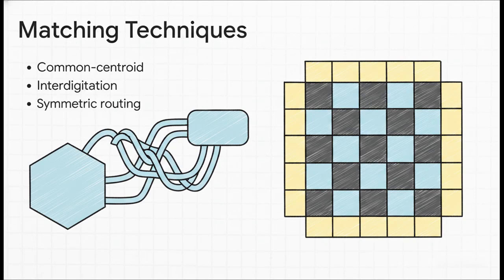Just imagine a current mirror with two matched transistors. If you route them asymmetrically, different via resistances and coupling capacitances will completely ruin the match. And boom, you've got a massive offset voltage. To fight back, we rely on vital layout matching techniques like common centroid and interdigitation. Instead of just plopping transistor A next to transistor B, we break them up into fingers and cross-couple them in a checkerboard pattern, like A, B, B, A. This is genius because if there's a thermal gradient or a chemical etching variation across the silicon, both transistors experience the exact same average error, effectively canceling it out.